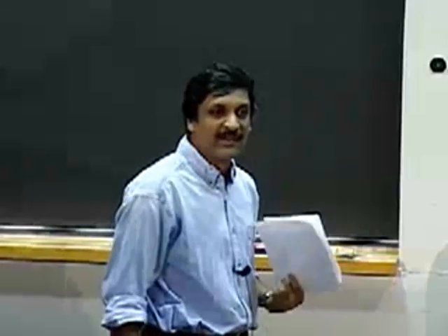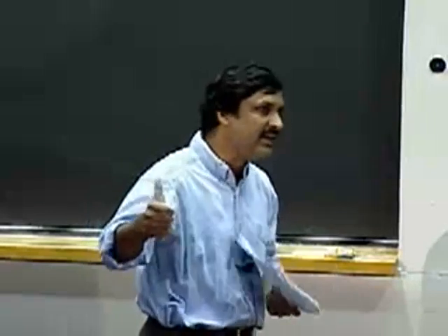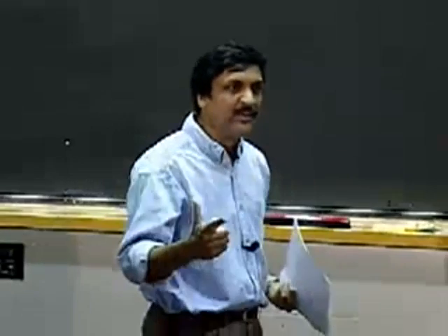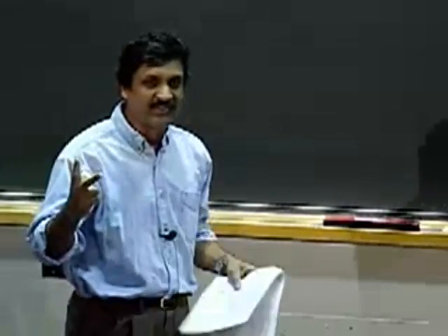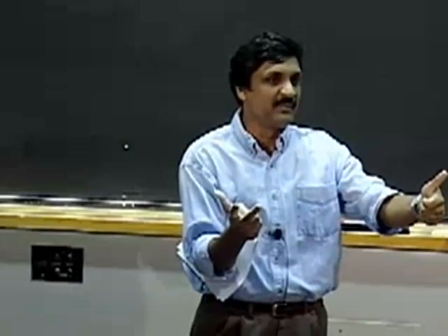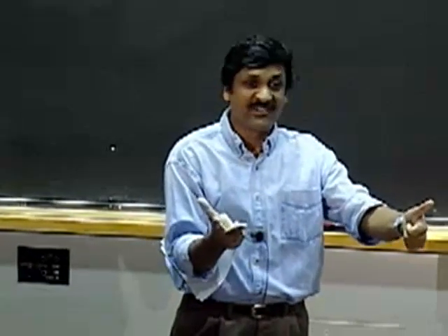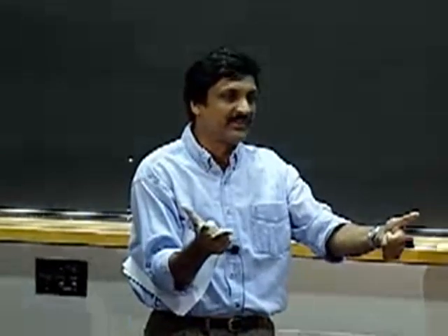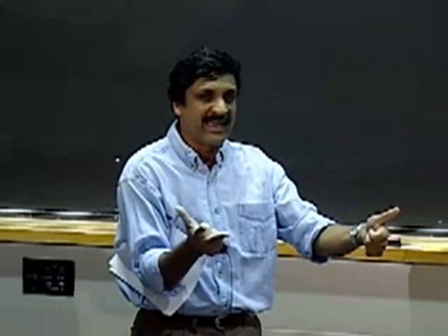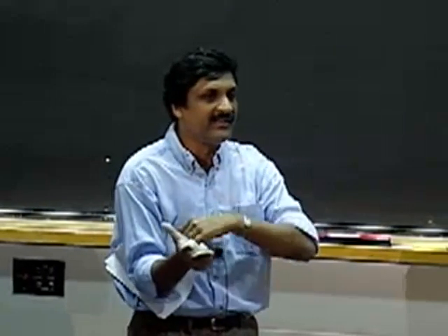Again, as I pointed out to you at the beginning of this lecture, no new foundations today, no new theories, no new disciplines, no new laws. We're just going to take what we've learned: three simple things, infinite gain, infinite input resistance, zero output resistance, plus this new thing, V plus equals V minus. Just armed with those four principles, we're going to charge ahead and analyze a bunch of circuits. It's a lecture on pure applications today.